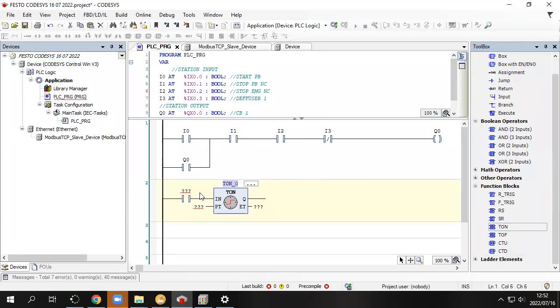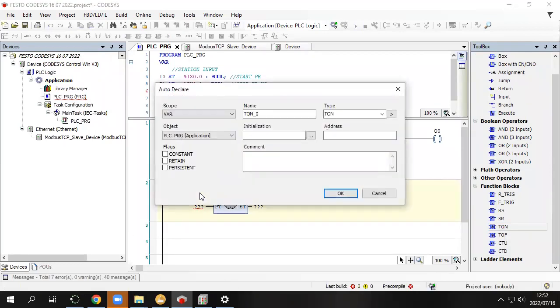So once you place something, you need to initialize it. You can rename it, or you can just click enter. When you click enter, it has what they call retain there. I don't think you should just retain there. I've never worked with a system with physical equipment where I used the retain.